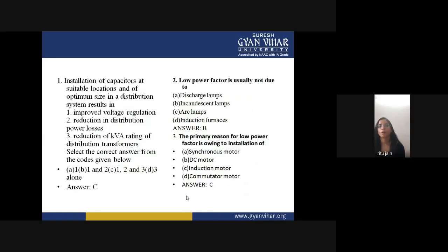So this is all about power factor and the power factor correction method. I want to summarize this lecture: power factor is always represented by cos phi, where phi is the angle between voltage and current. If your load is resistive, the power factor will be maximum, because in the case of resistance, the voltage and current will be in the same phase. So phi will be 0 and cos phi will be 1. So in the case of resistive load, your power factor will be maximum.